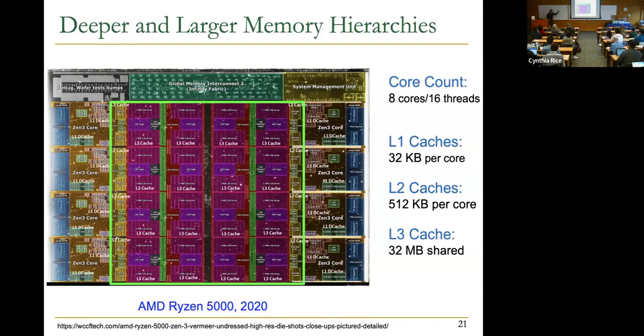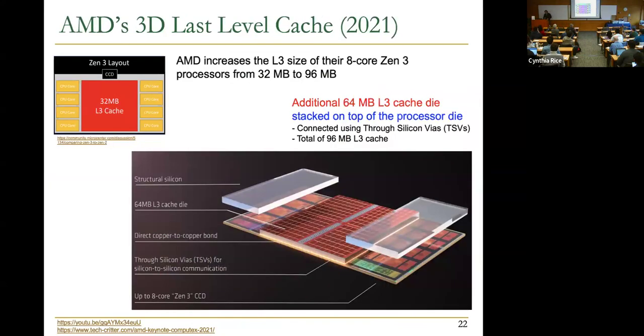If you don't like my picture, this is AMD's, one of the recent chips. You can see that that green box encapsulates L2 and L3 caches. And then there's the memory interconnect, et cetera, that I didn't encapsulate. So most of the chip is basically data movement and storage. And we're adding more of that with 3D stacking. These are beautiful technologies, but we're adding more caches and more data movement and storage with relatively little benefit.